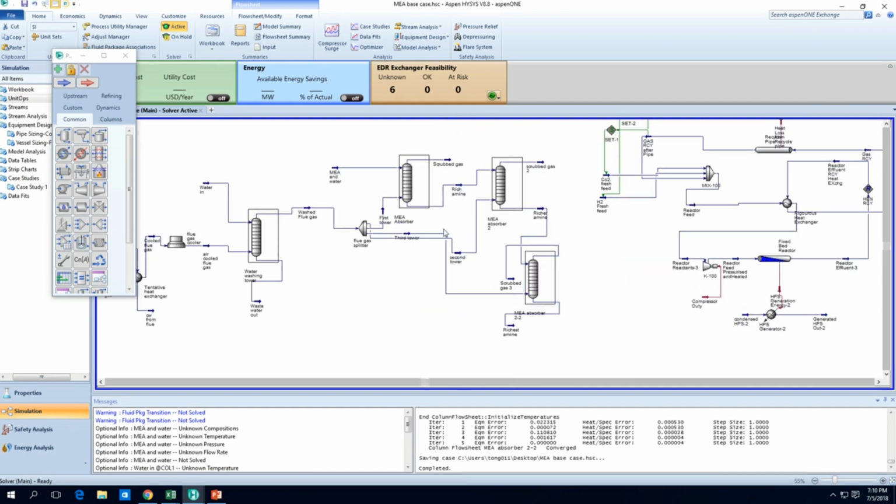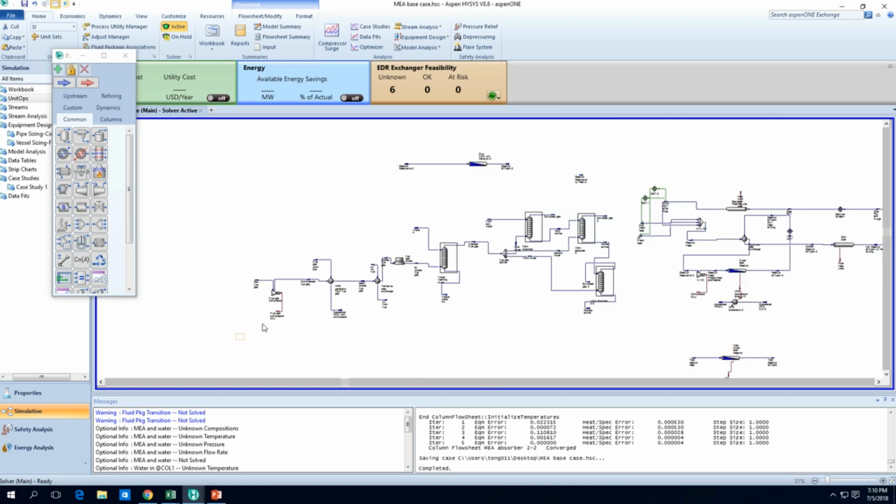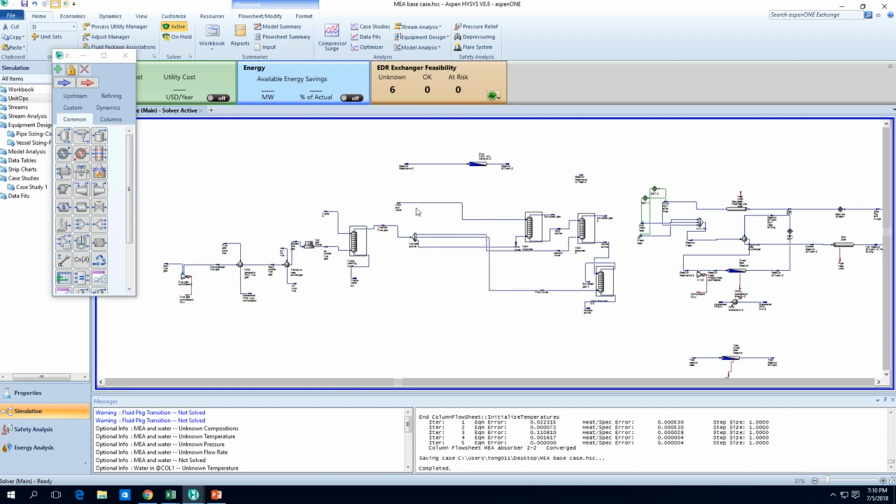I mean, you can always increase the amine flow rate, but that may have some trade-off. The more amine you use, the more you might have to replace, and not only that, I think maybe there's a higher stripper reboiler duty. All of these things can add up later on. But this is somewhat of a workable system.